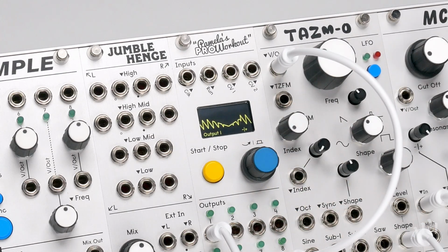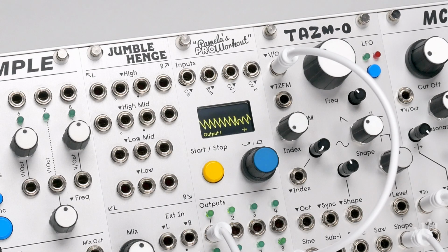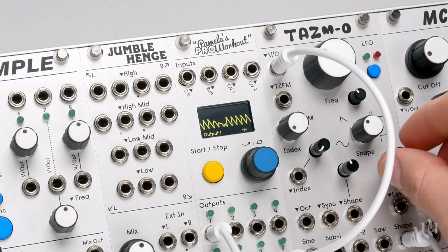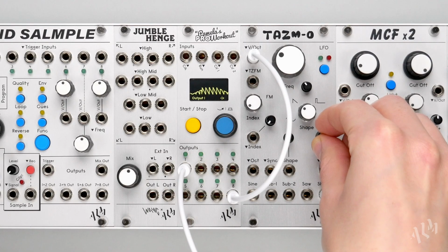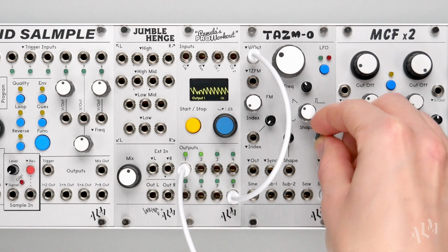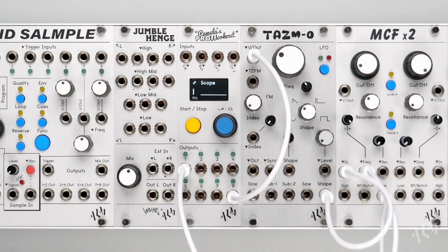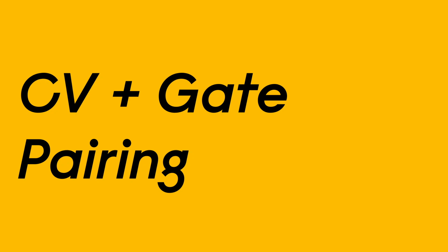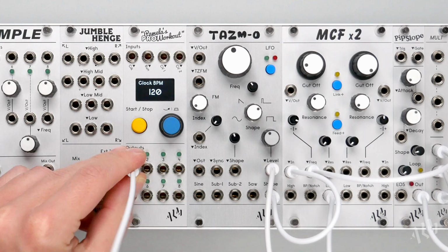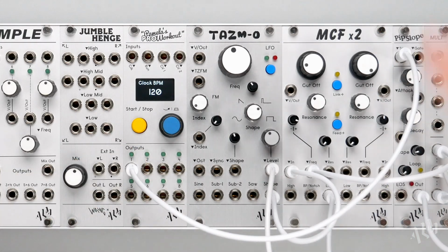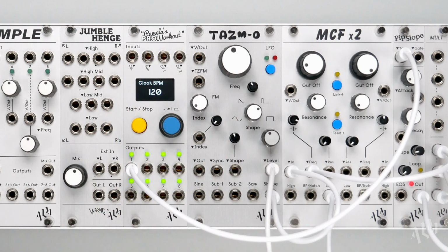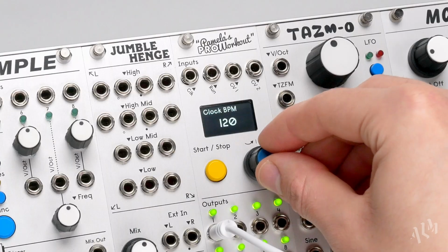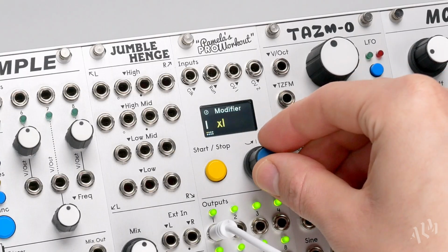There are endless possibilities for combining modulation with cross operations. The results are very dependent on the wave shapes, speed, and various settings of the two outputs. Another powerful use of cross operations is to tie together two outputs for use as a CV gate pair. Here, output 1 is patched to trigger the pip slope, controlling our synth voice.